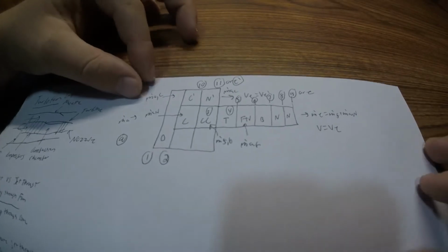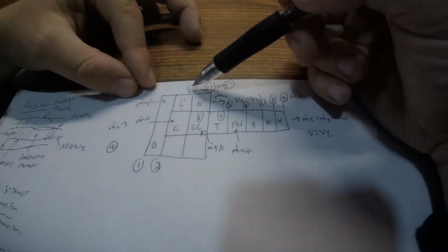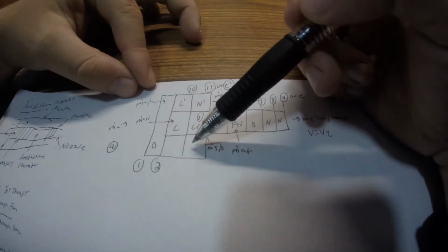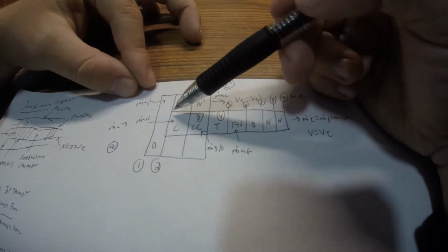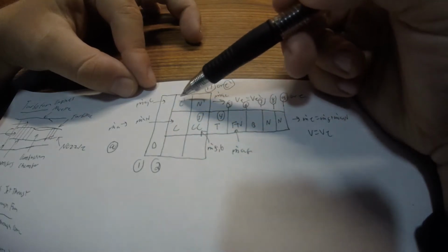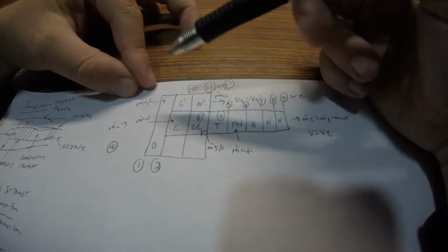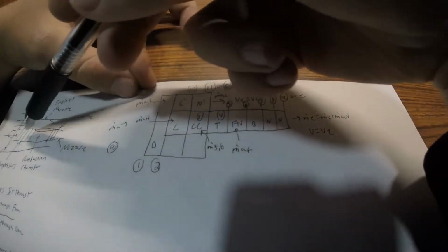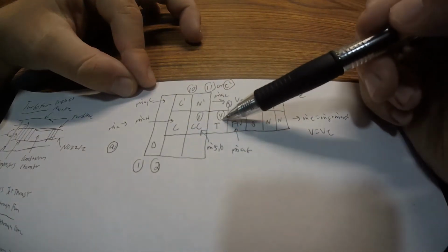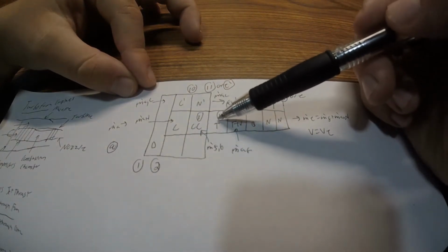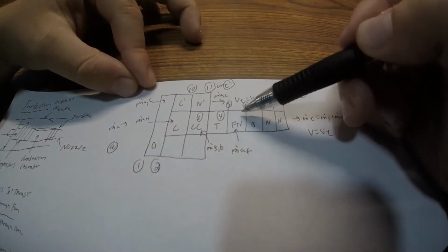Here's a kind of phase diagram where you can see all the different stations. We have the inlet and diffuser. For the outside fan part, we have the compressor, then a nozzle and then the exhaust. If the air goes through the turbojet part, we have a compressor, combustion chamber, turbine, and if there were no afterburner, there would be a nozzle right here and that would be it.